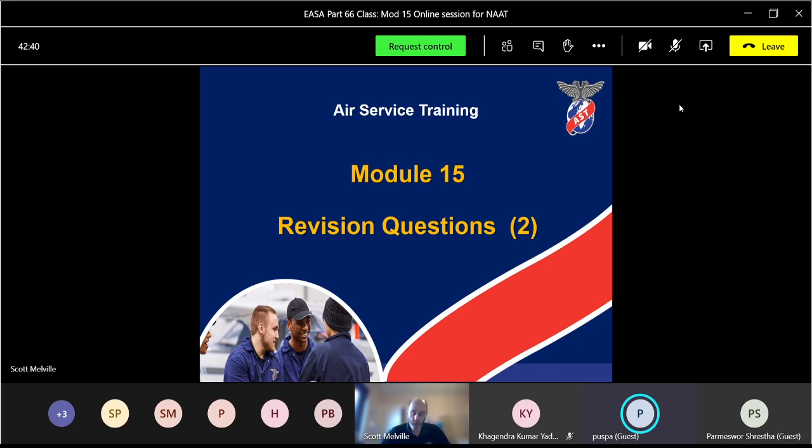What's the benefits of a digital fire detection system? It's very similar to the normal firewire. It looks the same, but it's now a digital version, so it does capacitive and resistive at the same time, but also good reliability. Reliability and accuracy. Yeah, I think we've got there. It's sealed, so there's less chance of getting moisture and debris and contamination there.